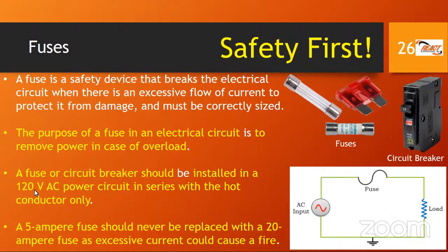And also for breakers, we need to be aware there's a place that you install a breaker in a circuit, and we need to know that both fuses and circuit breakers should be installed for AC power circuits in series with the hot conductor only, right? So we don't put it in the neutral, we don't put it on the ground, what we put it on is the hot. So that's an exam question, and the hot conductor, the hot line, is where we are putting our breaker in, not neutral and not ground.